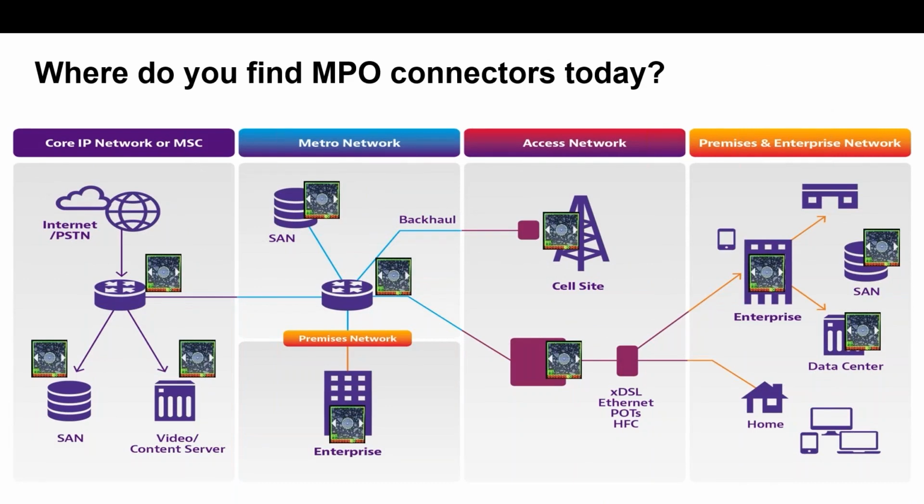So where do you find MPO connectors today? Pretty much everywhere. Anywhere there's fiber optic cabling being run, you're going to see ribbon fibers. We just did a big project with one of the major service providers where they're running MPO cables up the side of cell towers. So it's everywhere out in the field.